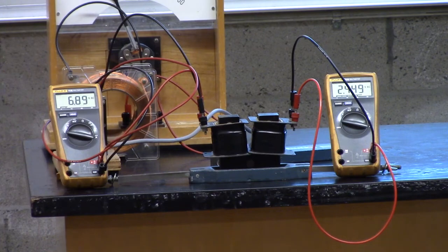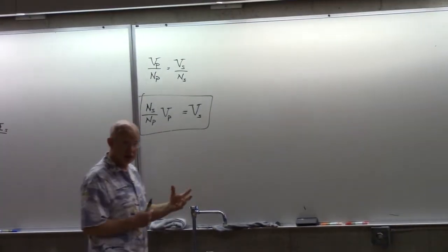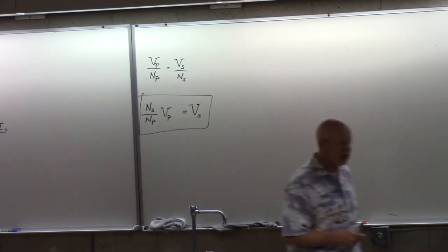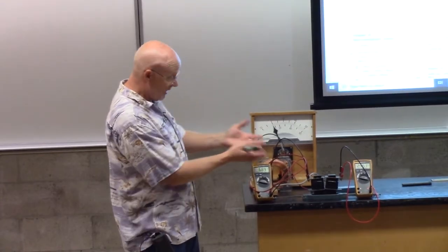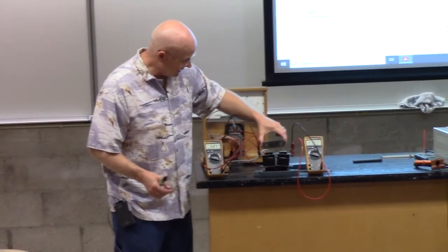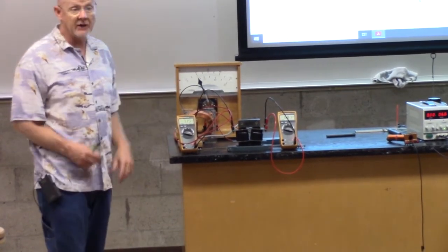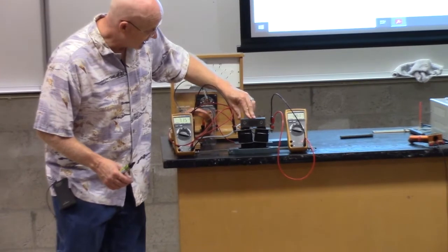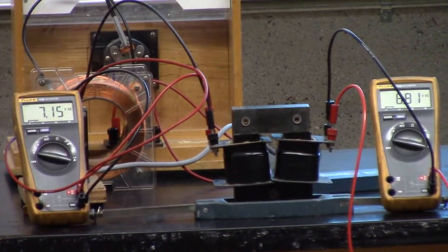And according to this math, if they have the same number of turns, and this ratio is 1, and so what I get in the secondary should be the same in the primary. There should be no increase or no decrease. And obviously, if I don't get all the flux in there, there is a loss. And so something like this, there's a huge loss. Something like this, there's a little bit of loss. So I would say here, most of the flux is getting through.